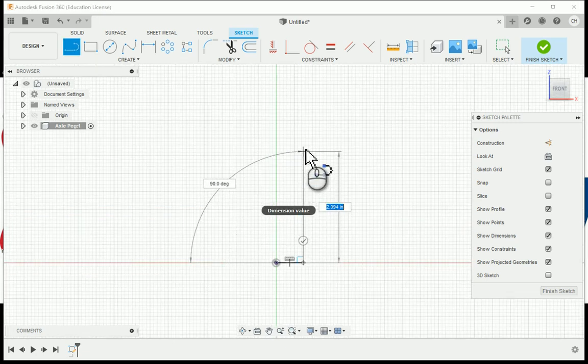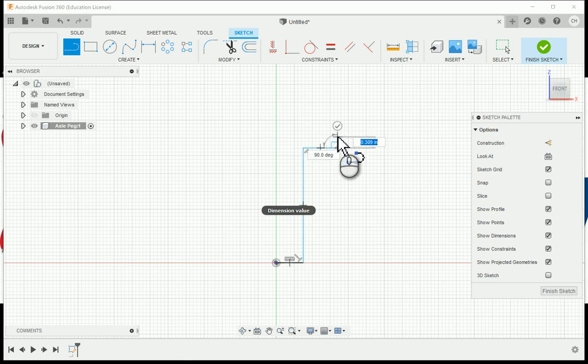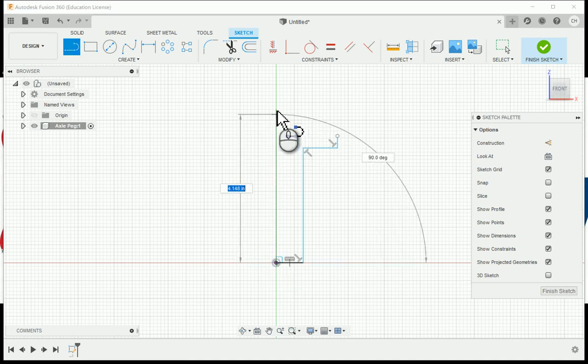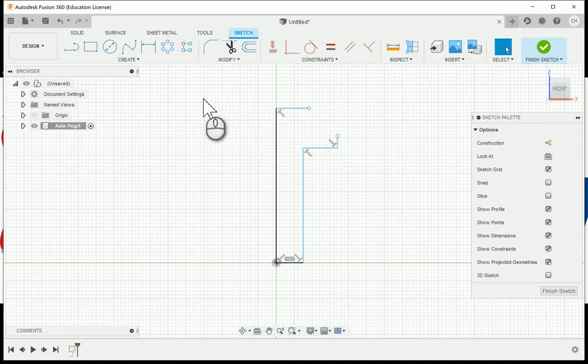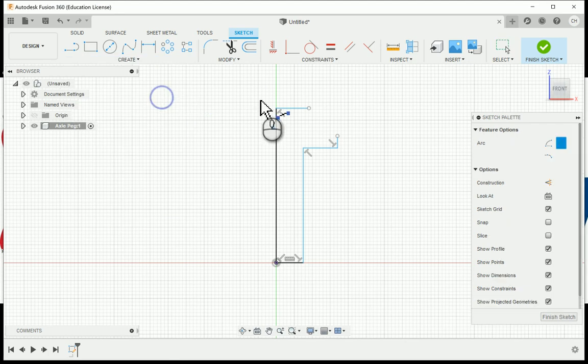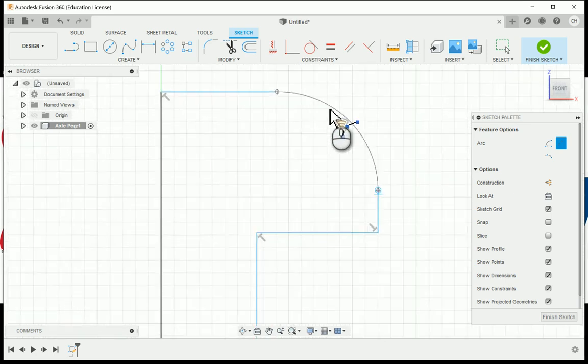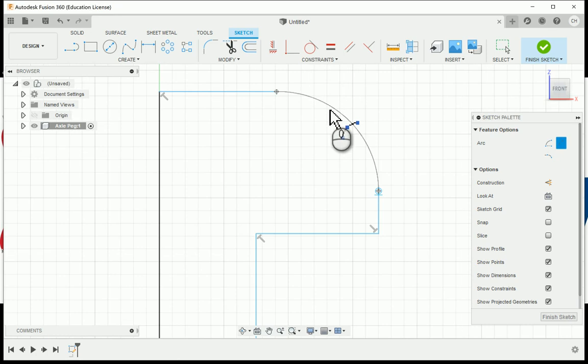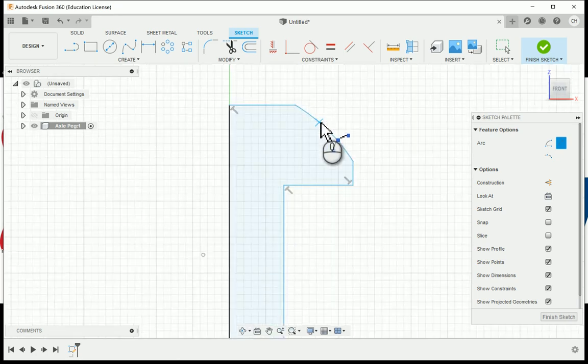I'm going to do very similar to what we did with the train wheel, and we're going to be revolving our profile around an axis. Now I've left the sketch open. I'm going to create a 3-point arc, and I'm going to choose the endpoints of the white dots here. Now I don't want to make this really rounded like this because it's going to create a tangent constraint, so I'm going to make it just a little bit flatter like this.